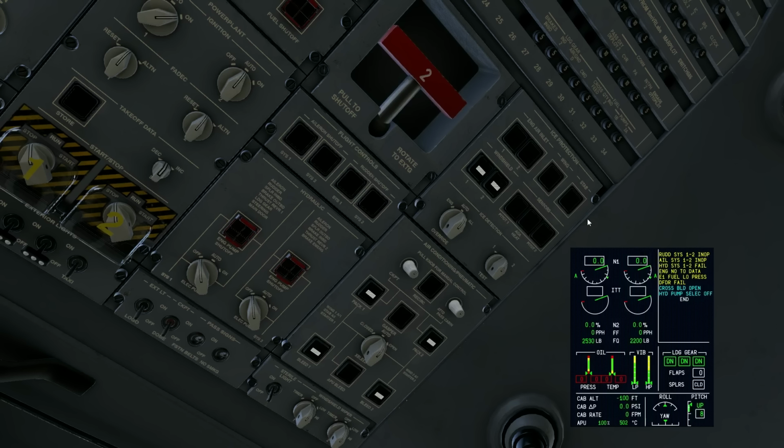These are all electrically heated and have a scheme to them on when they're heated. Remember dark cockpit. Dark cockpit says if it's normal for flight, it's dark. So the sensors are on their own logic. We don't really need to interact with them very often. We can deselect them if there's a failure or something that requires us to reset them. But for the most part, these are kind of dust collector buttons because they live pushed in. These all come on when the engine starts.